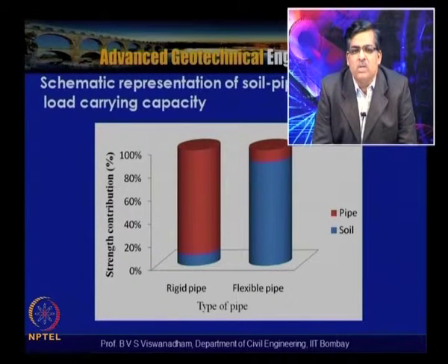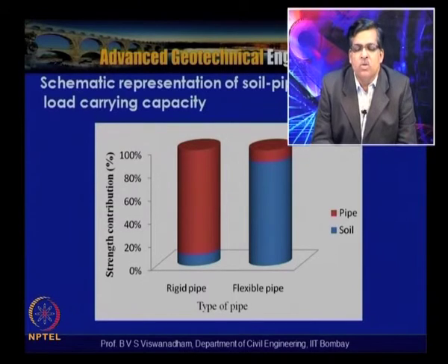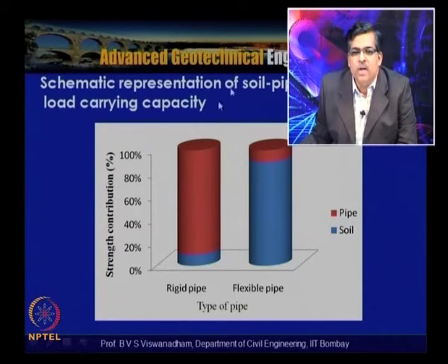This particular slide shows the strength contribution percentage on the y-axis, and rigid pipe or flexible pipe as the type. It clearly shows that for pipe and soil contribution, the load apportioning capability of rigid pipe is very high compared to flexible pipe.